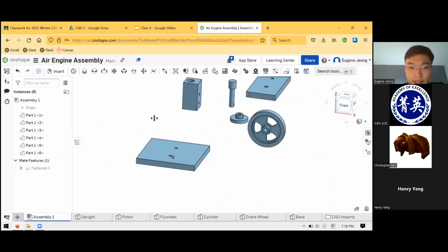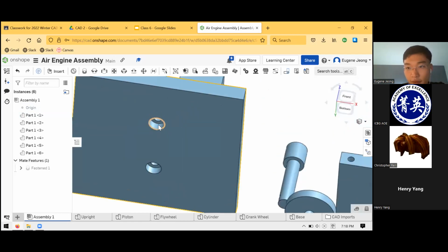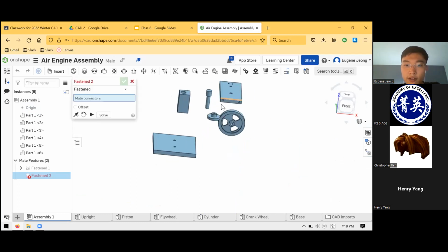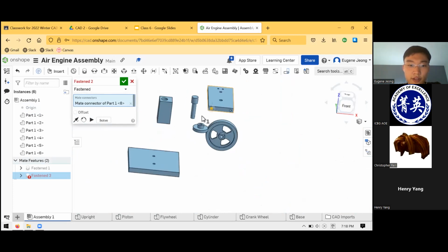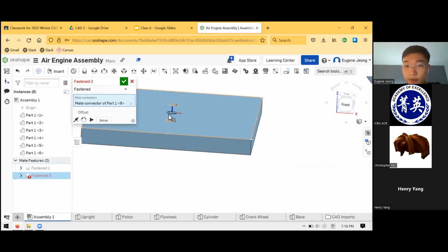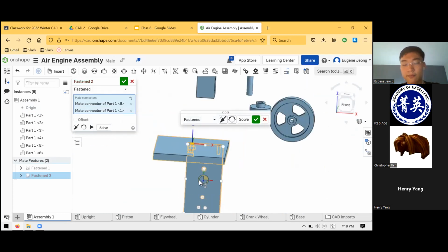And the reason for that, you can imagine, like I said, is that the counter bore is there so the head of the bolt can sit on the part and be flush with the bottom surface. So the bolt's going in this way through the bottom where the counter bore is, and then it's threading into here. The reason this hole is threaded is so that the screw can come in through here, and the part that sticks out is threaded, and it would thread into the upright.